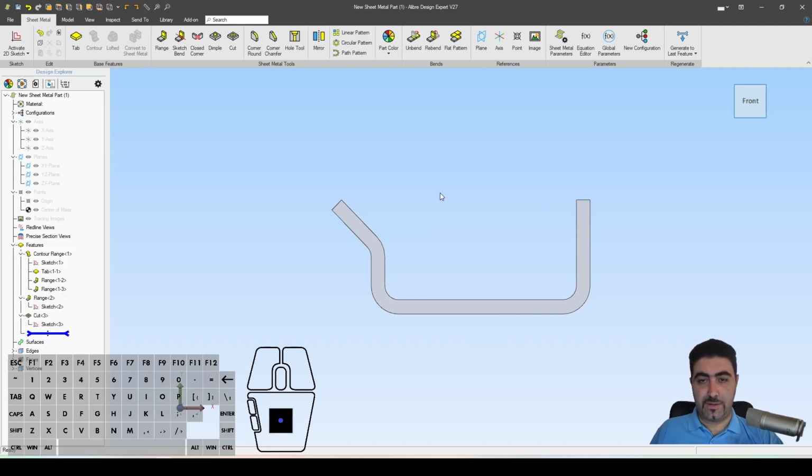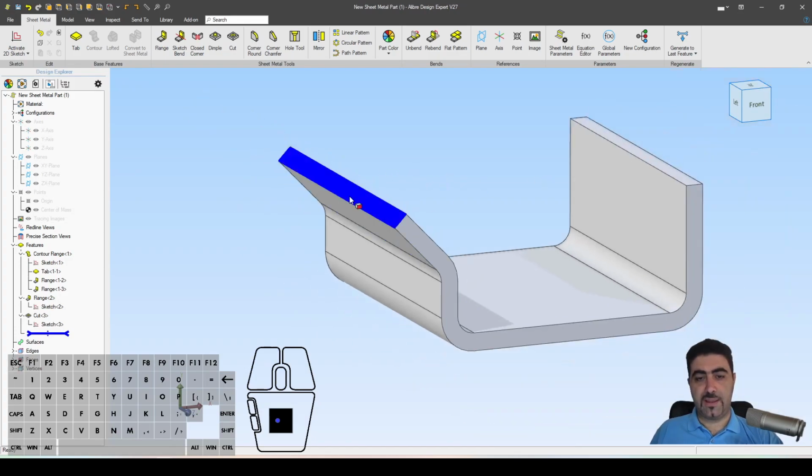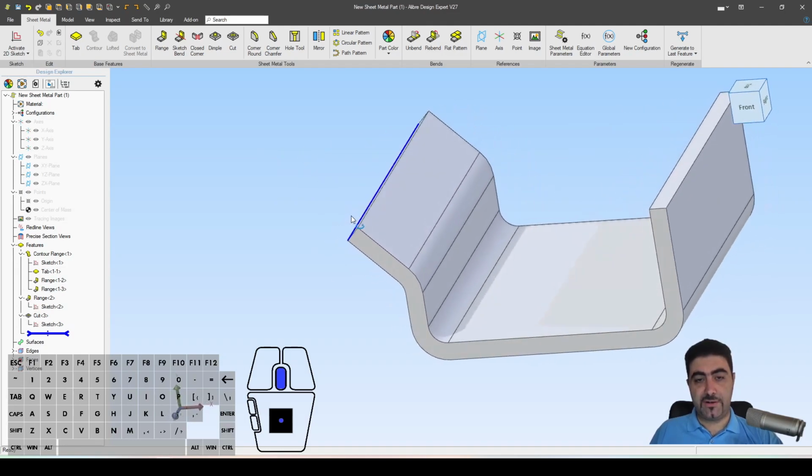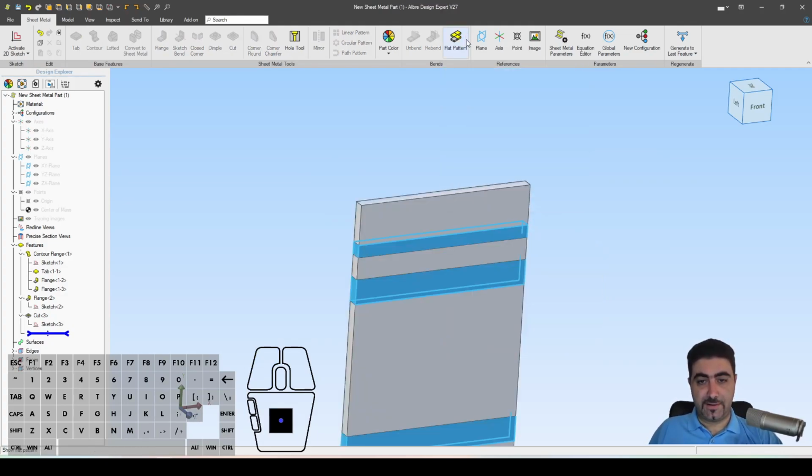I cut this way, in this direction. So it cut here, and instead of making this face be along the direction of the cut, as would happen with a regular extrude cut, it made it perpendicular to the rest of the faces. So this can remain a 2D cut when you flat pattern it, right?